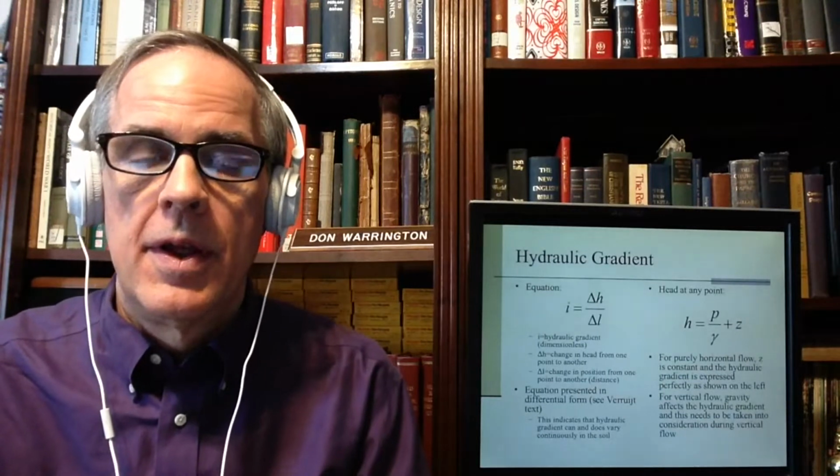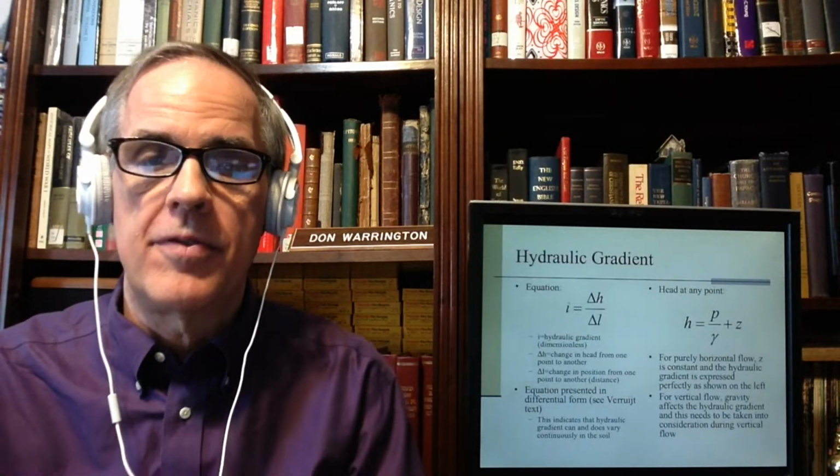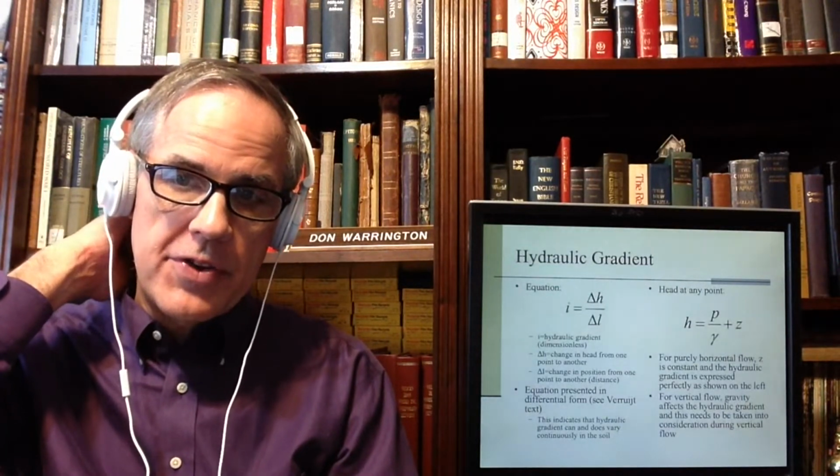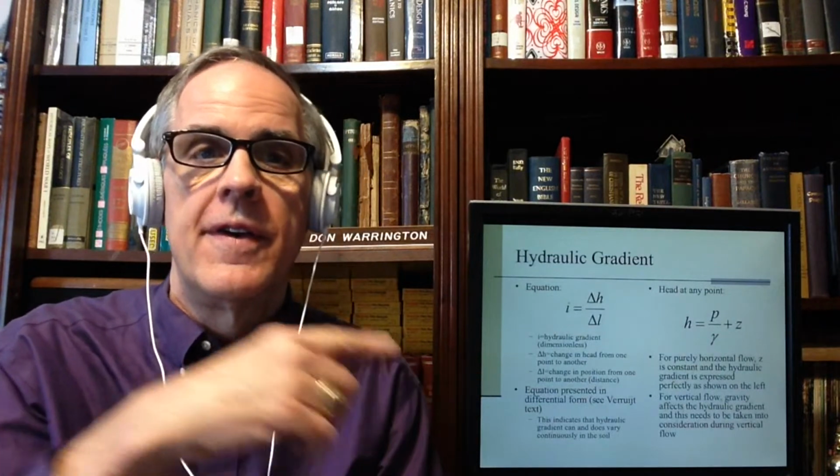Another thing we want to talk about, I don't throw a lot of things at once, is hydraulic gradient. Hydraulic gradient is equal to the change of head over the change of length. And you'll notice that the head at any point, like I said before, is a function of the pressure and the gravity. Most all water flow we're going to talk about here is driven one way or the other by gravity in the soils.